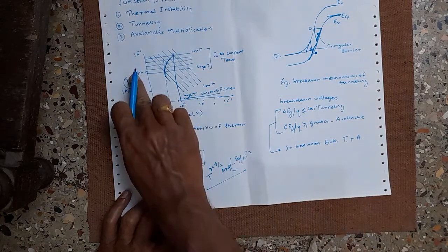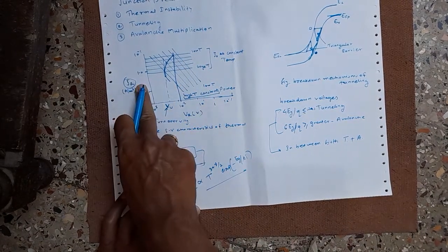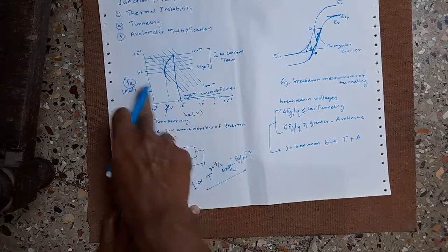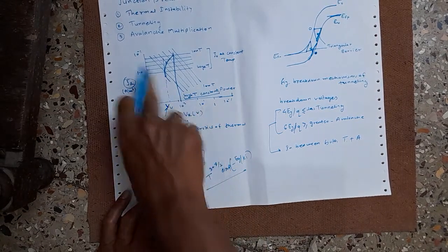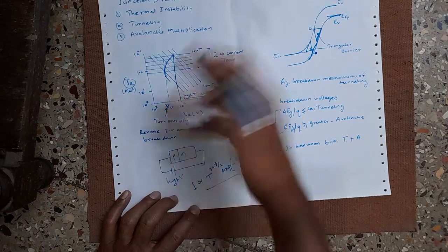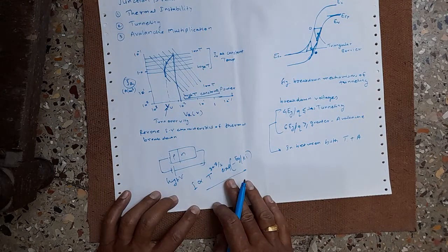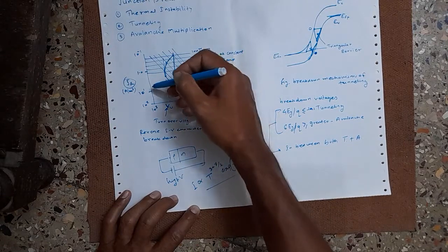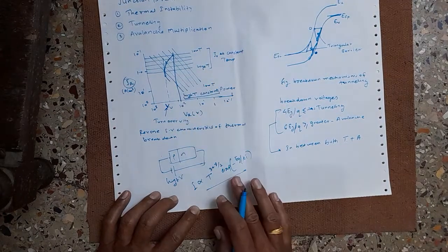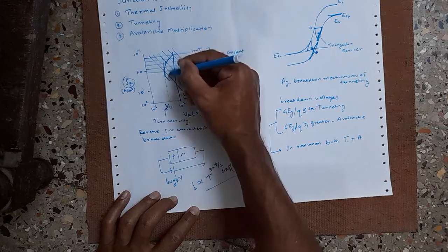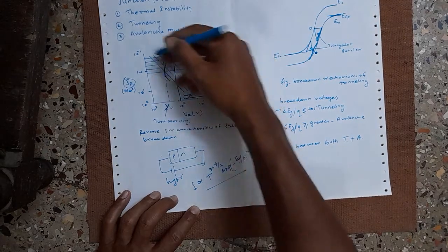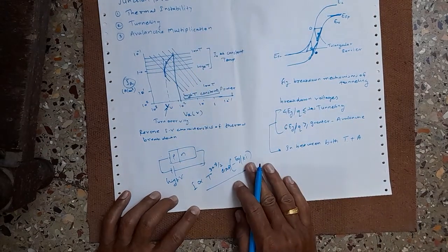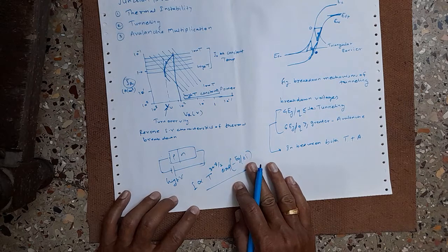Power is nothing but the current times the voltage. So we know that this is the current and this is the voltage. If we take the product of that, the area under that curve gives us the power. And the sloped lines, or straight lines in the log plot, give us these hyperbolas, right? So if we have these sloped lines, they give us the corresponding hyperbolas.